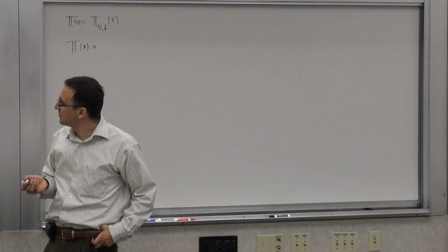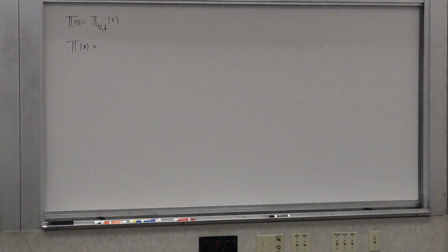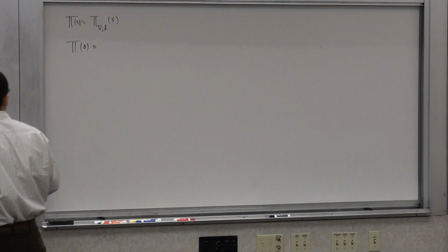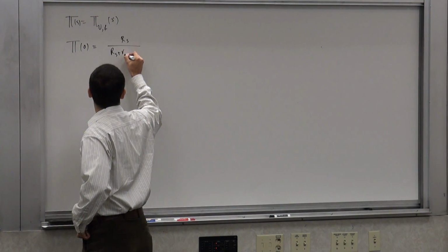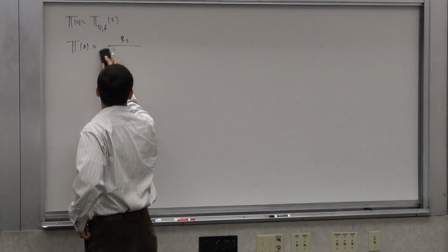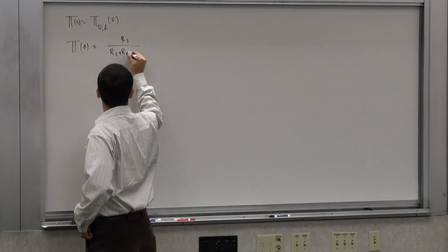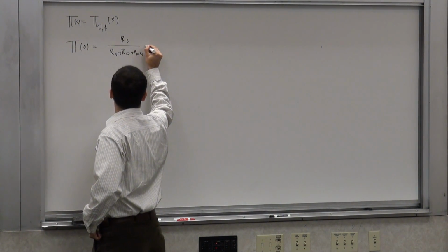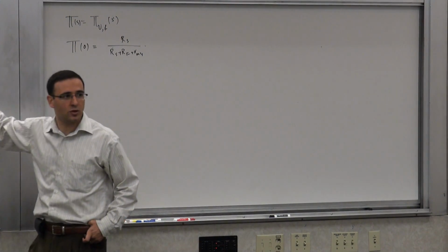I have an Rm here, I have an Rf here and an Rs here. So it's a voltage divider between them. So it's Rs over Rs plus Rm plus Rf. Okay, and then I have the three gm1R1, gm2R2, gm3R3.